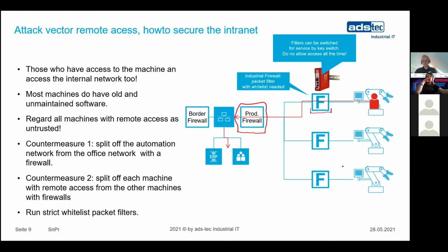So regarding the second risk, with this foreign machine, where the machine is under attack itself or is unworthy of your trust, you have to protect against this path. So the attacker should not be able to use a machine to attack the second one. Even the neighborhood, maybe some machine of your, in German we say Mitbewerber, I don't know the English word. So what can you do? You can put in here a firewall packet filter. So this is not an allowed data path. It's the easy go. We call this whitelists. A whitelist inside of the firewall allows only listed traffic. So for example, if there is really a need for this data path, maybe it's only for some single special PLC protocol, but not for file shares or something like that. Then you have to do a strict filter, and then you're on the better side.